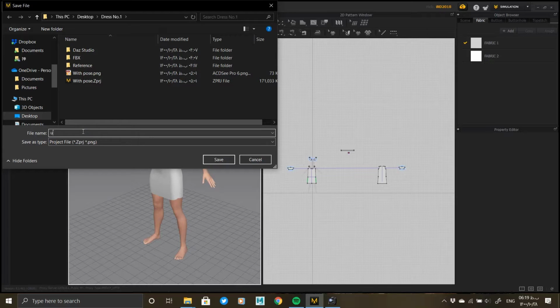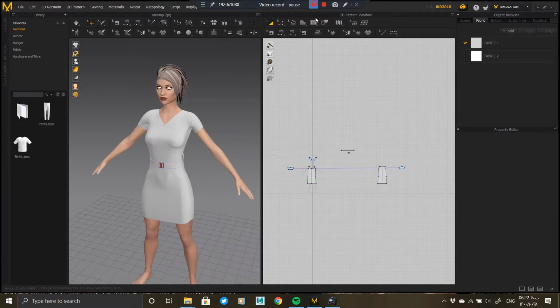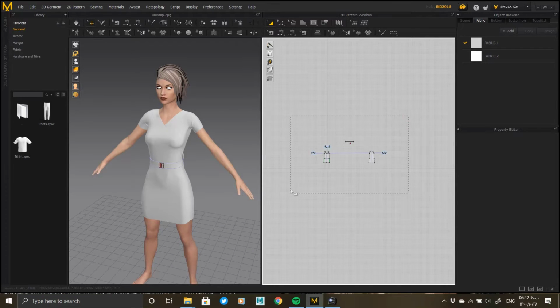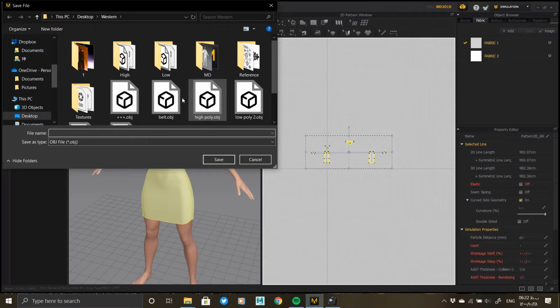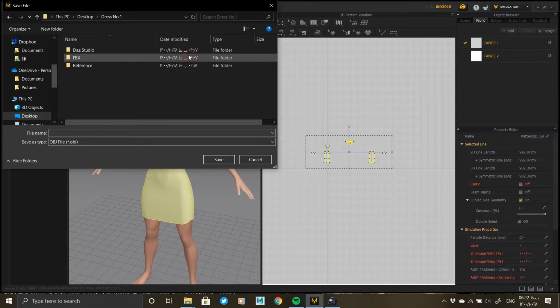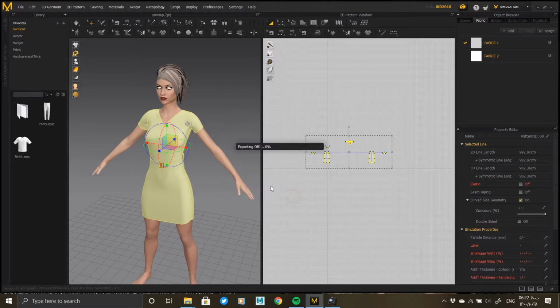Save the output as OBJ without characters. Select the single object mode, and choose one of the 3 modes, thin weld, thin unweld, and thick, based on our needs. In thick mode, the thick parts' UV is not defined. So in the case of thick output, it is better to define the UV thickness separately, for other parts in that software. UV is applied to this output, but it is not set as UDIM, and we need to identify each of the UVs, and define it as a polygroup, so that we can create material on each of the UVs separately.